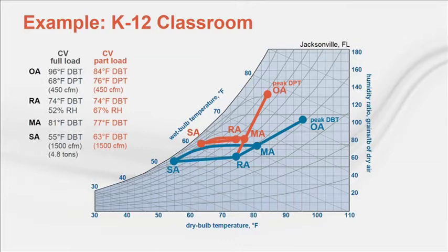Meanwhile, the compressor cycles on and off, which results in a warmer average temperature delivered to the zone. Although this control action successfully maintains the zone dry bulb temperature at set point, the cycling compressor reduces the amount of moisture removed and zone humidity rises.